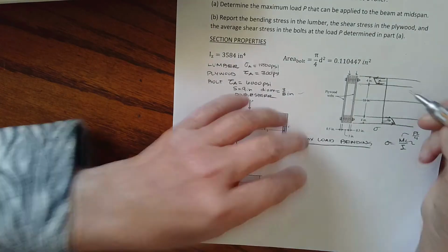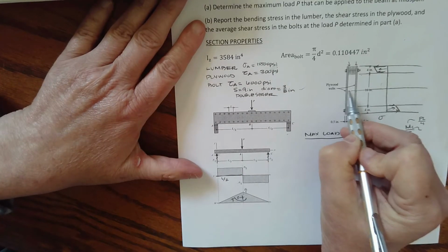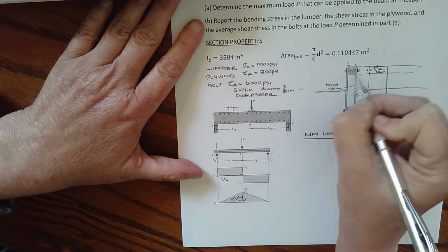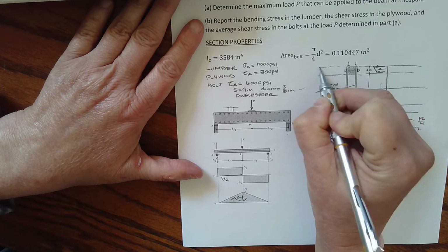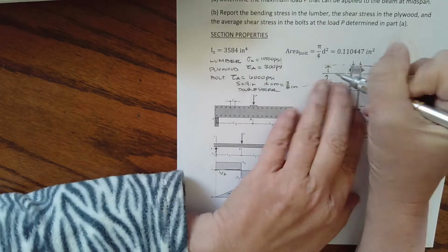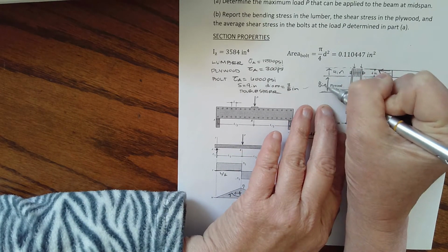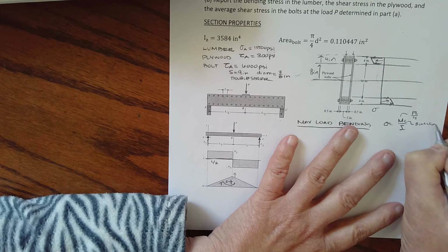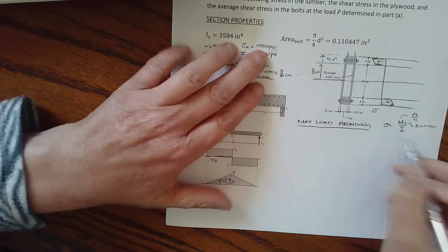C is that outermost fiber, and I have to understand that's where the largest normal stress develops. So we are going to go up, and then we're going to continue up. So we are up 4 inches. If this is 16 inches, this is 8 inches to that point. So it's going to be 8 inches and then plus 4 to get to that outermost fiber. And then our moment of inertia is given and our allowable stress is given.